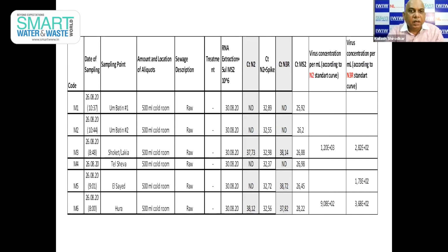So one more query, Clive, is what's the virus identification method and the time taken for the result? So the identification method is, once we extract the samples from the sewage, we use qPCR analysis to identify the virus. There are some very unique and proprietary testing methods to identify the virus in wastewater. The results are very, very rapid. If you have access to qPCR, you can get the results literally within a couple of hours.